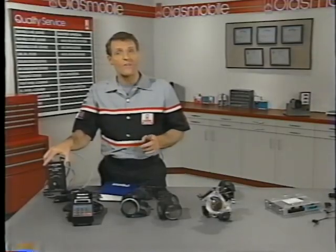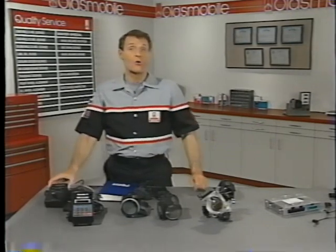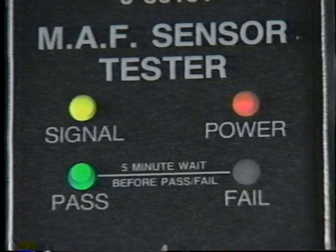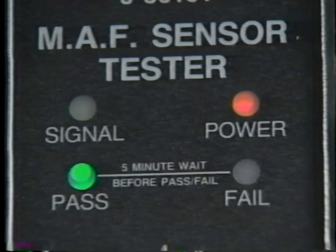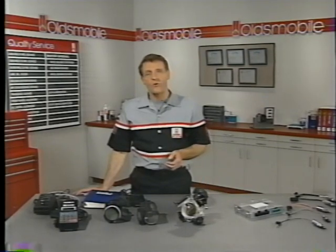Be sure to follow the instructions for using this tester exactly. It's easy to condemn a good sensor by using bad procedures. The static tester is useful if you suspect an intermittent sensor malfunction. With the tester connected and the pass light on, lightly tap the electronics module of the sensor. If there is an intermittent malfunction, the pass light will briefly go off as the fail light comes on. Of course, you can also perform this tap test while you observe the MAF signal on an oscilloscope.